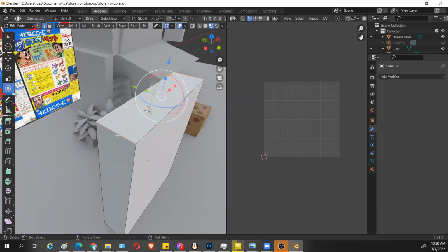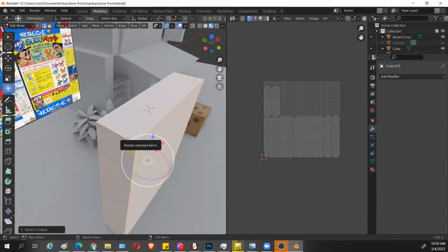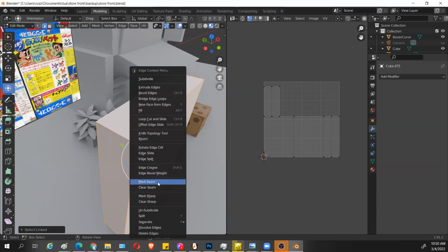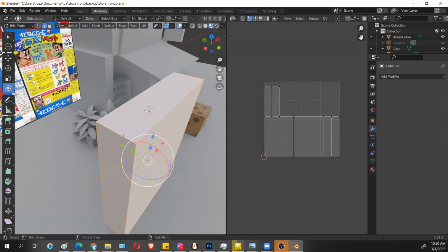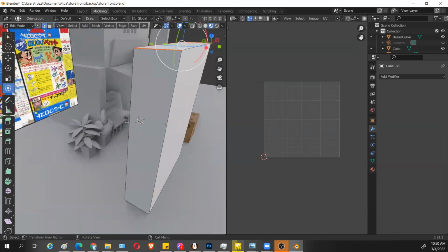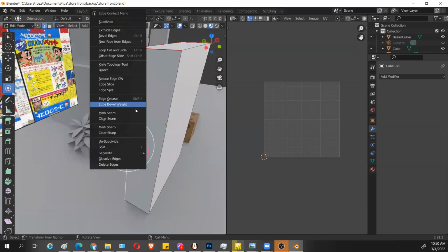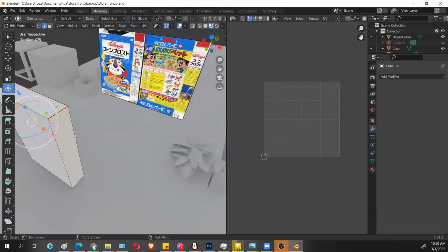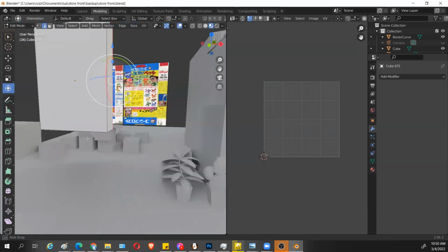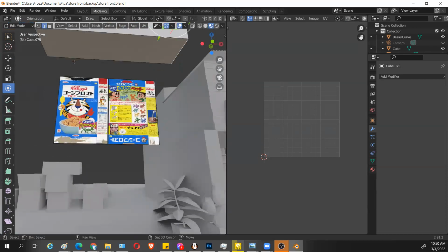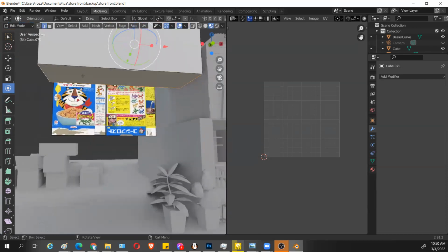Okay? So click this. Okay? Then right click, clear seam. Okay? Select the edges on top. So 1, 2, 3. Right click, mark seam. So it becomes black. Okay? Then we're going to click here. Right click. No, not that one. We're going to click here. Ito yung bubuksan natin. Right click, mark seam. So we're marking the areas where we are opening it for our UV texture.